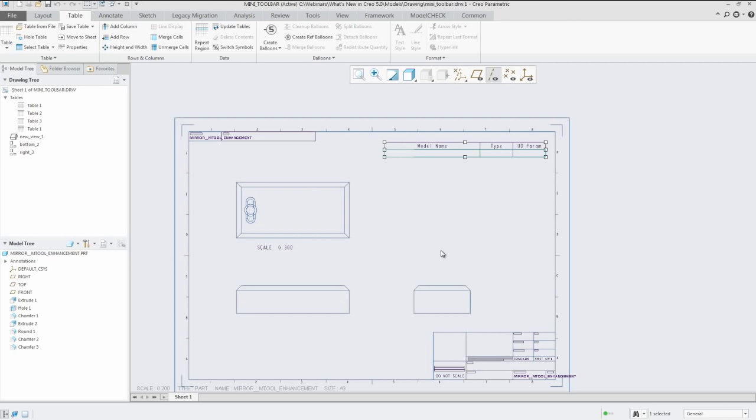Another one is that in Creo 5 there's improved performance for large assembly drawings. The multi-threading algorithm for hidden line removal calcs in drawing mode is further optimized for large assemblies, because the computations involved in HLR calcs are typically time-consuming. These computations contribute significantly to the time it takes to perform commands such as opening a drawing, updating a drawing or a drawing sheet, as well as most actions triggering a repaint of the drawing. So using multiple cores or processes saves time and improves efficiency when updating views of large assemblies.